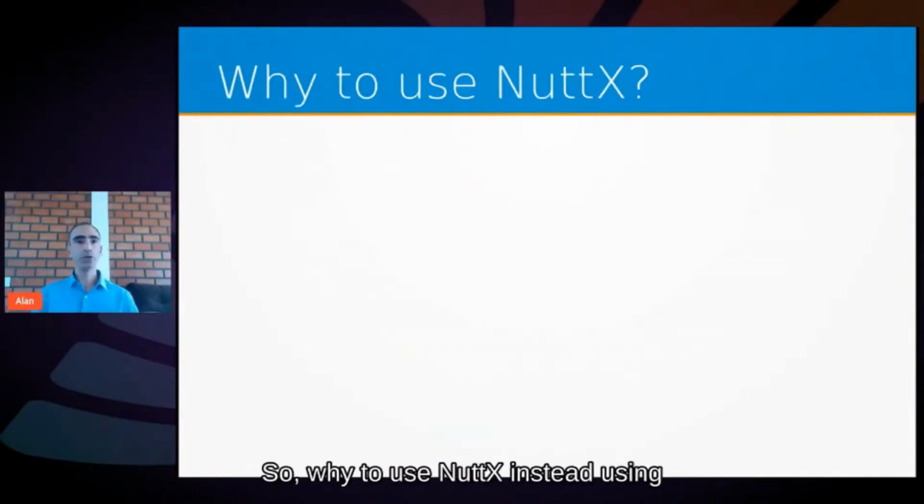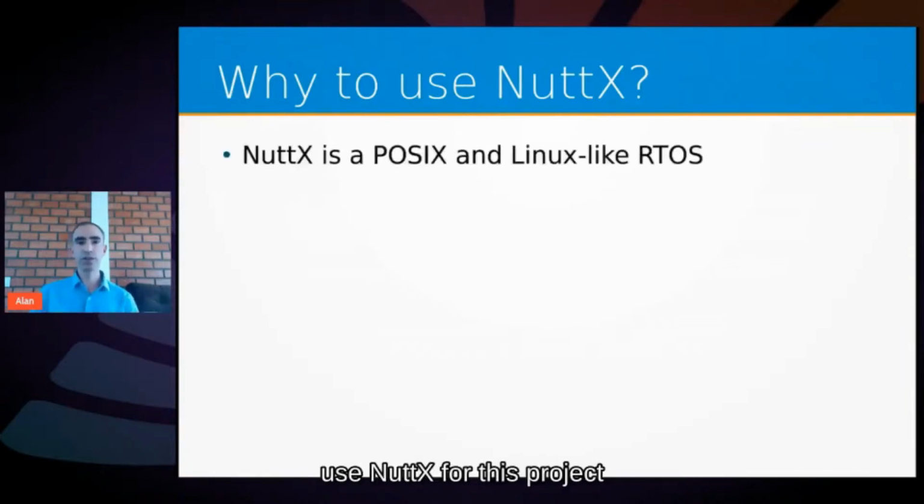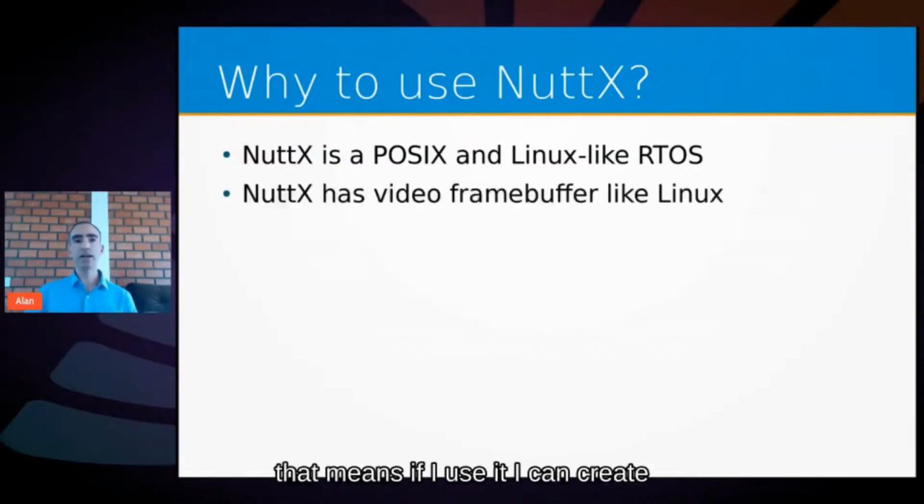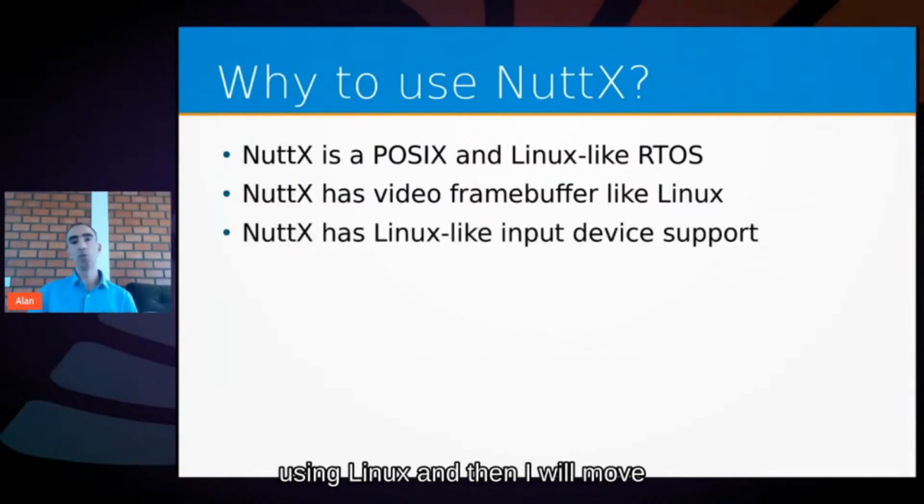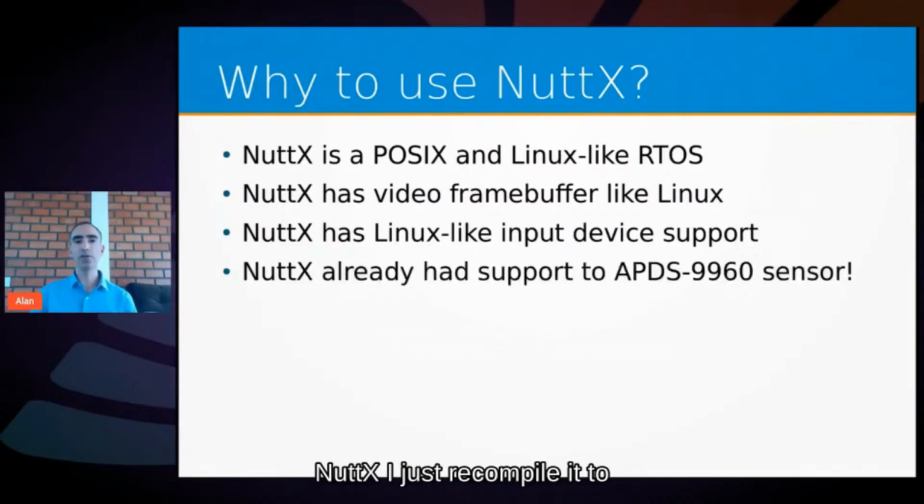So why use Nuttx instead of Arduino or even some simple RTOS? Why use Nuttx for this project? First of all, Nuttx is a POSIX and Linux-like RTOS. That means I can create the program using Linux. I can develop the logic and the interface and so on using Linux, and then I just recompile it to Nuttx.